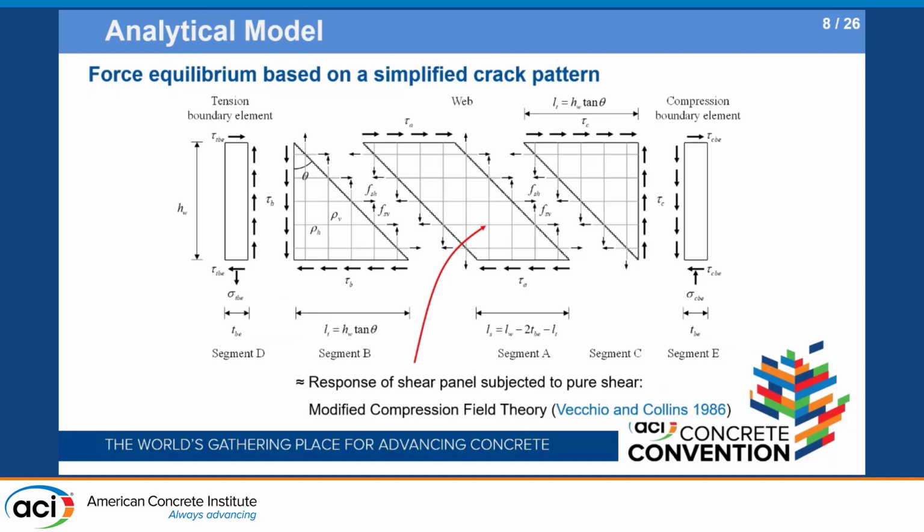Yeah, so this is a proposed numerical mechanics-based model, which is just a force equilibrium of the squat wall. Based on the typical crack pattern of squat walls, we divide the wall into 5 constituents. According to the force equilibrium, once we get the stress of bars in the web, we can successively calculate the stress demands applied to the boundary elements.